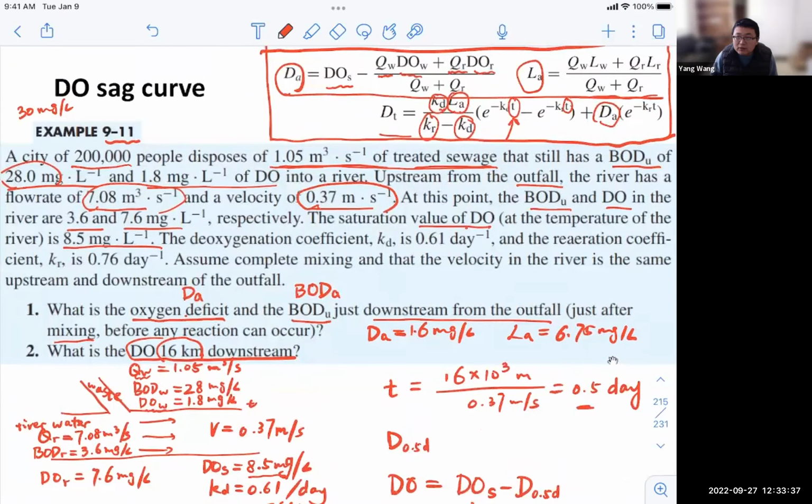Yes, this is just for river water quality. If you have a lake or a pond, then I would say it's more dependent on how fast the mixing is. If you can assume it's a CSTR, then you can evaluate how time is going to have an impact on the system. Since we talk about CSTR, for this river here we're actually treating it as a PFR, a plug flow. So there's no mixing along the river, but there's mixing across the river.